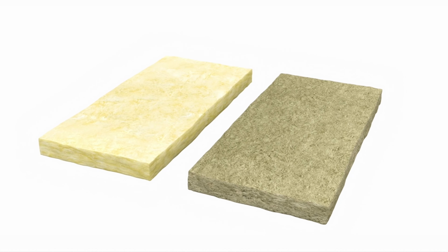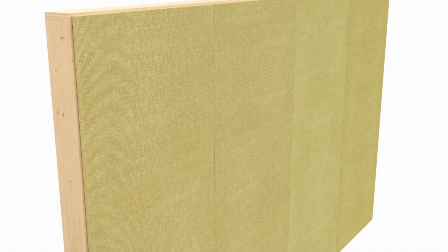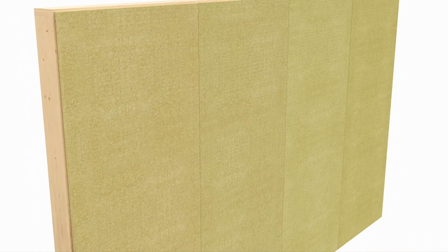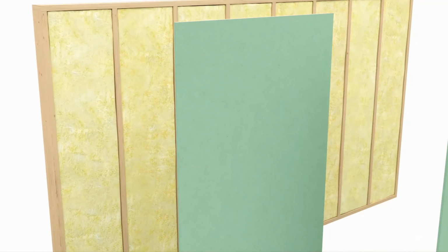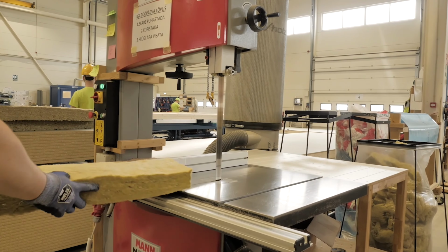The main insulation between the studs is soft mineral wool with a lower density, while higher density rigid wool is used as the wind barrier covering the frame to protect the penetration of outside air into the main insulation. Other option is to use wind barrier plasterboards. During insulation work, gloves and a dust mask should be used, as insulation materials can irritate the skin and cause coughing and itching.